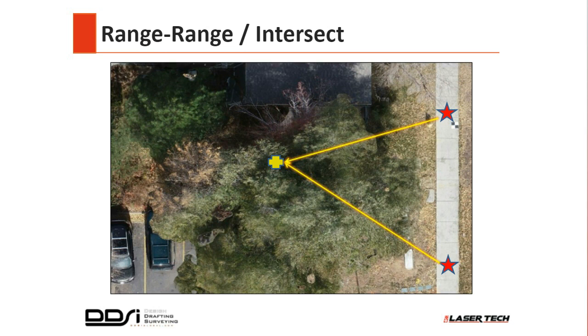Right, but again, in an urban environment like this, you can't really trust that the compass is going to be 100% reliable. There may be something buried just on the sidewalk there that might screw you up. So range is just a real safe, accurate way to go, isn't it? It's perfect for this one because the utilities are densely laid together down here in this area. So having that extra accuracy was the difference for this particular set of utilities.